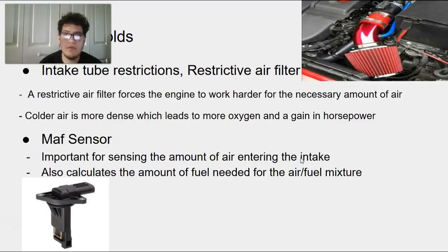Some more ways to get power and performance would be through the intake piping and the air filter. A restrictive air filter forces the engine to work harder for the necessary amount of air. Colder air is more dense, which leads to more oxygen and a gain in horsepower.